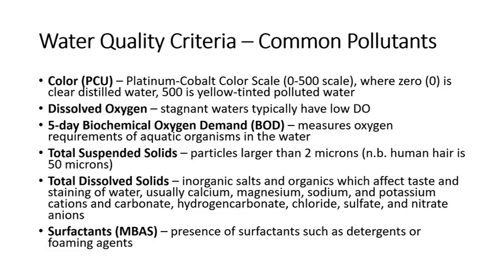Next is the total dissolved solids. These include inorganic salts, organics, and other compounds which affect the taste and staining of water. And this typically includes calcium, magnesium, sodium, potassium, and other cations, and carbonate, hydrogen carbonate, chloride, sulfate, and nitrate anions. Surfactants or MBAS. This test is to detect presence of surfactants such as detergents or foaming agents.